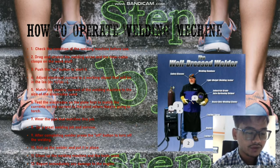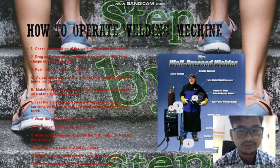Nine, after completing welding, press the off button to turn off the welding machine. Ten, roll up the welder cable and put it in place. Eleven, clean up the welding machine and the tools used. Twelve, report immediately any damage to the engine.